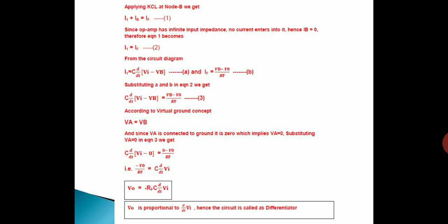And according to the virtual ground concept, since VA should be equal to VB, VB also should be 0. So substituting the value of VB in equation 3, we get C into d by dt of Vi minus 0 is equal to 0 minus V0 by Rf. We got this equation just by substituting Vb equal to 0 in equation 3.